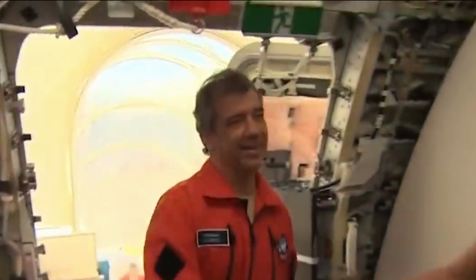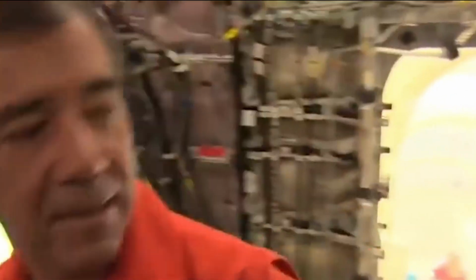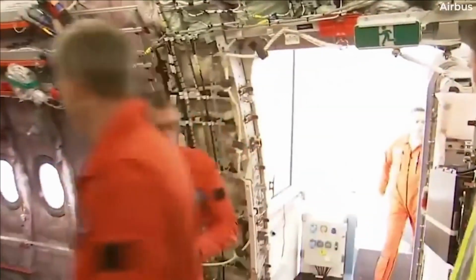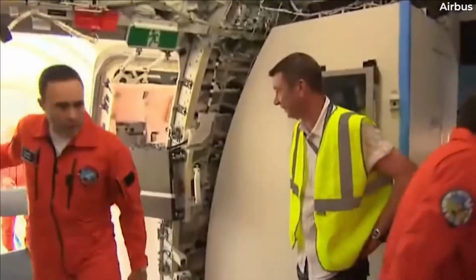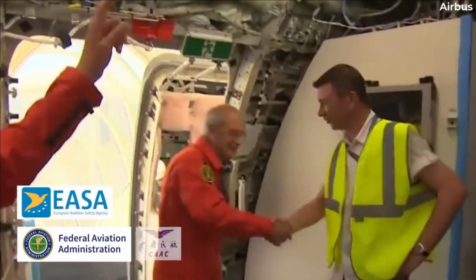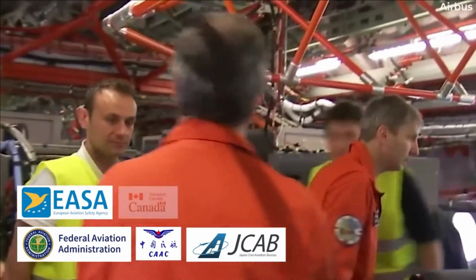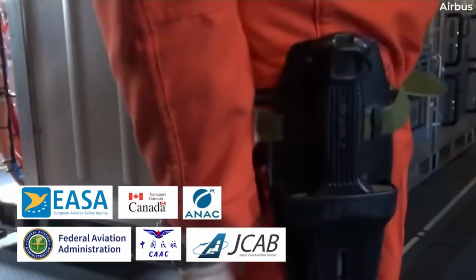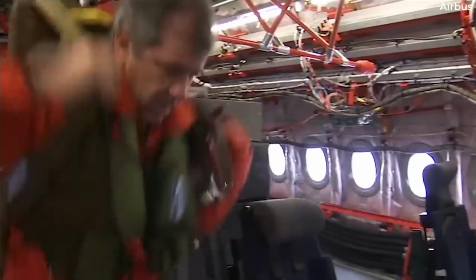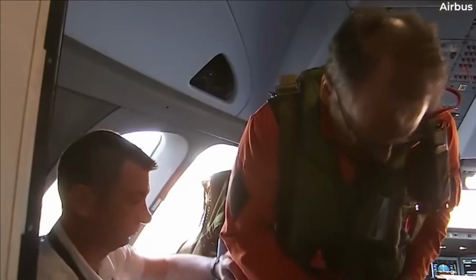Current inspection status of the airplane, including the time since the last inspection required by the inspection program that the airplane is maintained under. 7. Current status of applicable ADs, including the date and methods of compliance, and, if the AD involves recurring action, the time and date when the next action is required. 8. A list of major structural alterations. 9. A report of major structural repairs and the current inspection status of those repairs.